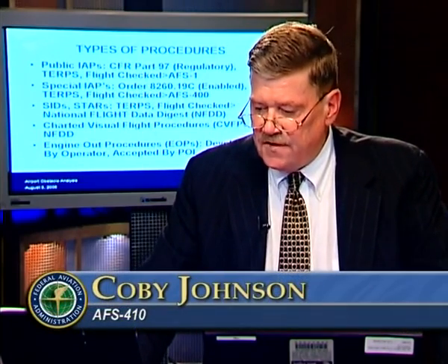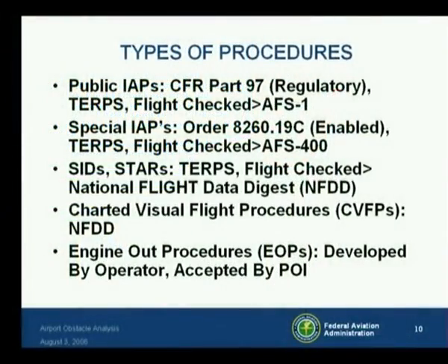That's the one that belongs to AFS 420 in Oak City, and that's a Flight Standards document signed by Jim Baylog. It's enabled by Part 97, so it's also regulatory. Those procedures are built according to TERPS criteria, they're flight checked, and they're approved by us here in Washington in AFS 400. Now, SIDs are developed by AJW, what used to be AVN. STARs, curiously enough, are still developed by air traffic. However, both are flight checked, TERPS criteria is applied for obstacle assessment, and they are not published initially in the NACO documents. They're published in something called the NFDD, or the National Flight Data Digest.